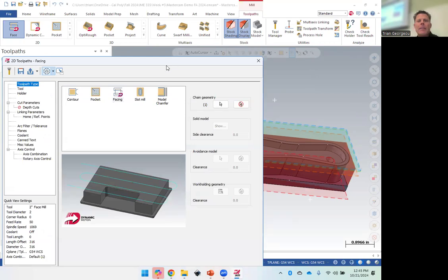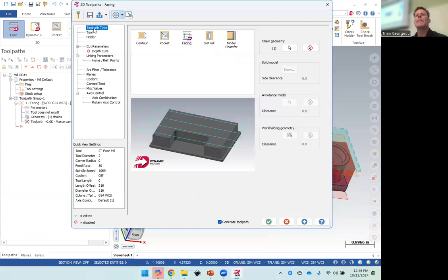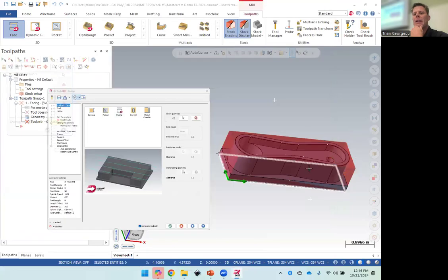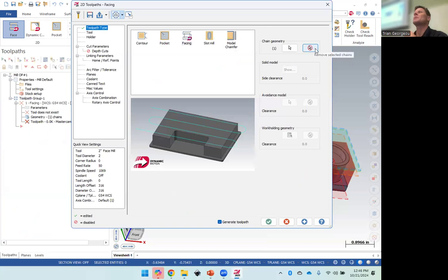And this is the classic Mastercam window that you're going to see for most of your tool paths. So this is how you build your entire tool path right here. This window with all these parameters. In fact, this first window right here, the tool path type, we've already selected everything in here. It's there in case you needed to change it. So I already picked facing, right? I already picked the geometry. I can click the button. It shows me my geometry. I hit check mark. If I hit this, it would delete my geometry. It'd be bad. So that's pretty much what this menu does.